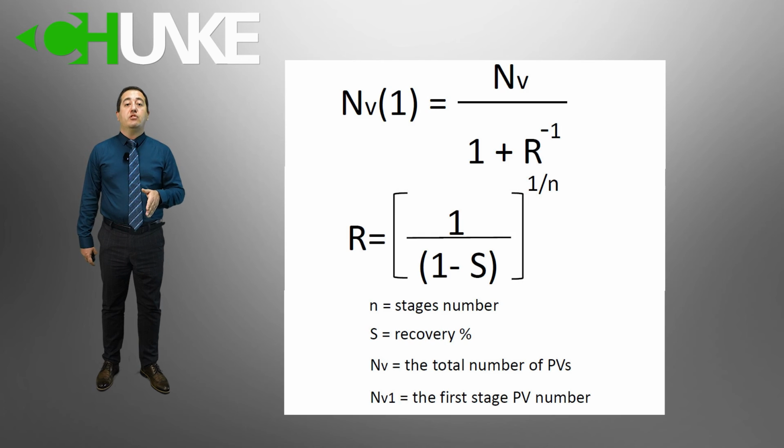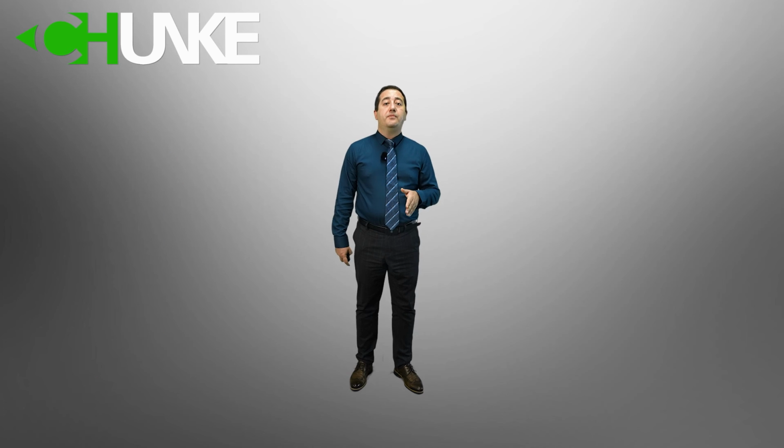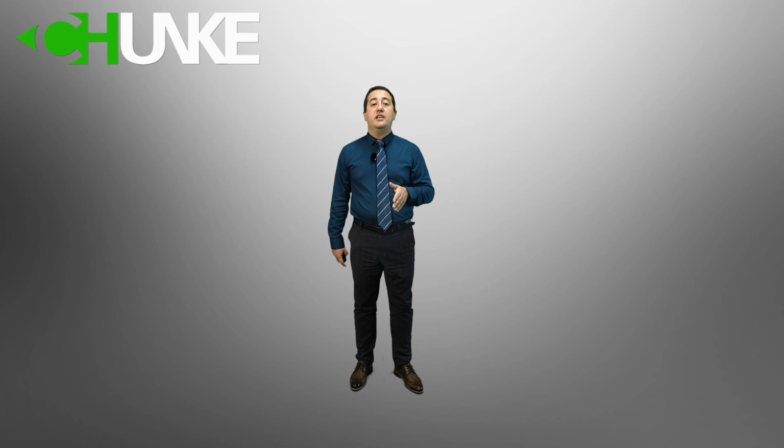The staging ratio R of a system with n stages and a system recovery S as a fraction can then be calculated with this equation. The number of pressure vessels in the first stage can be calculated with the staging ratio R from the total number of vessels.